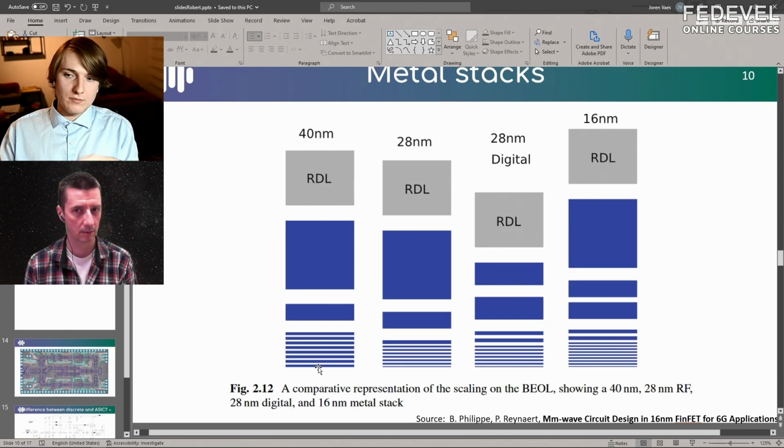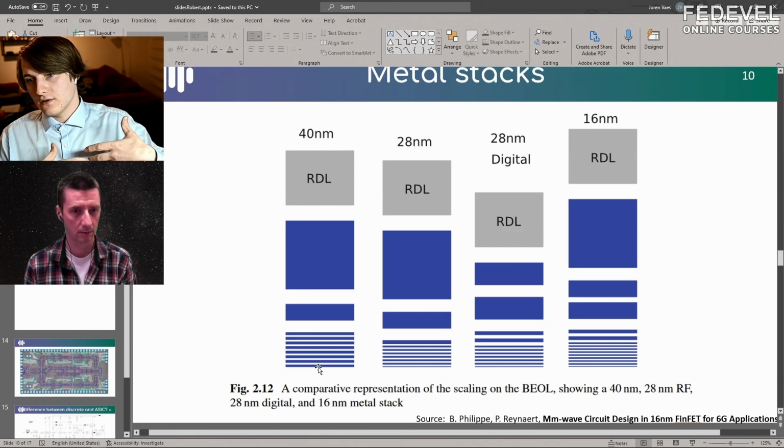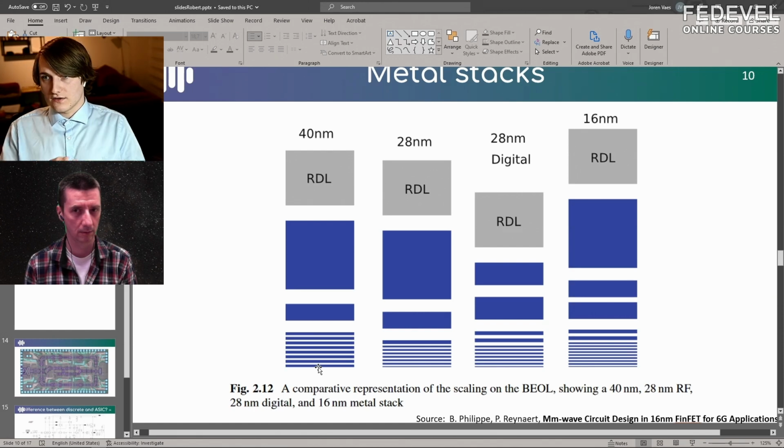Because they're thin, that means that the minimum line width that they can etch is also very low. So for example, you might have a 40 nanometer or 30 nanometer wide line that you can make with very narrow spacing, so you can get high density. But obviously they have high resistance, right? Because it's a very thin wire. You might have multiple ohms per square resistance.